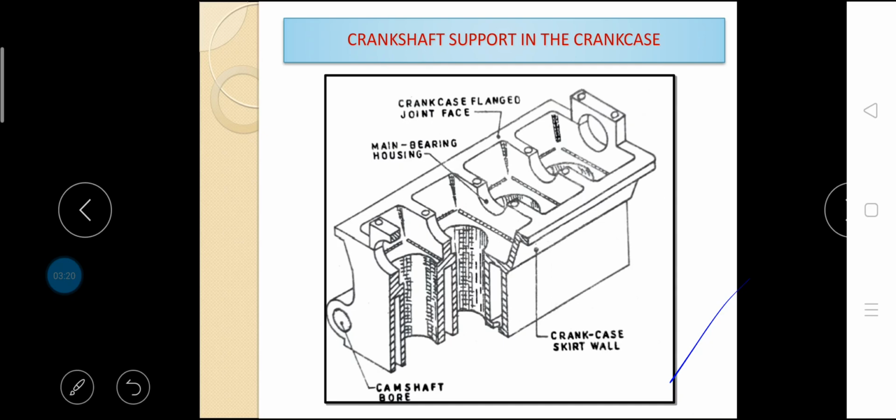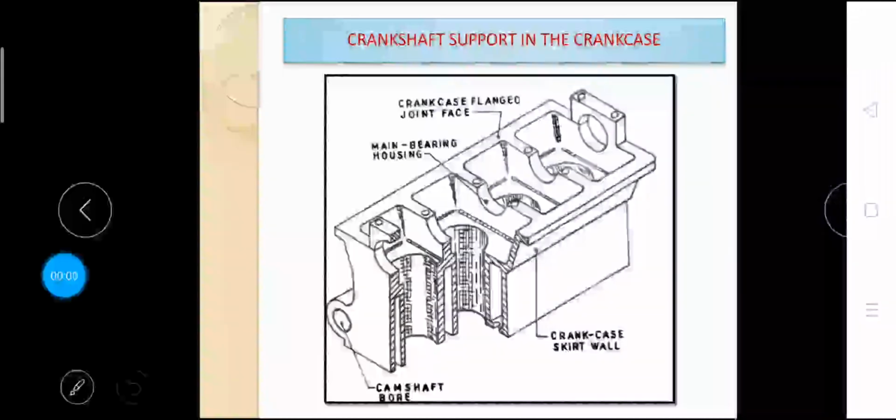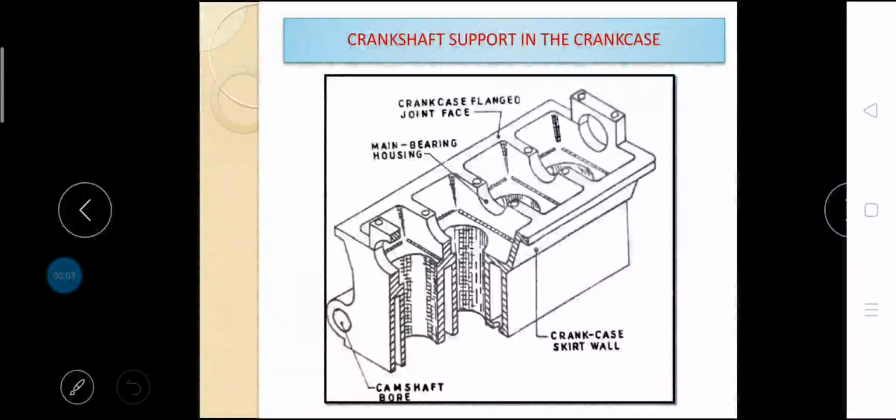The function of the camshaft is to effect the opening and closing of the inlet and the exhaust valves for each cylinder. Camshaft may be mounted in the cylinder block or head, or even above the cylinder head. It is always placed parallel to the crankshaft. When in the cylinder block, it is mounted to one side of the cylinders, either low down just above the crankshaft or high, slightly below the cylinder head. The camshaft is supported in usually 3 bearings in the cylinder block bore.